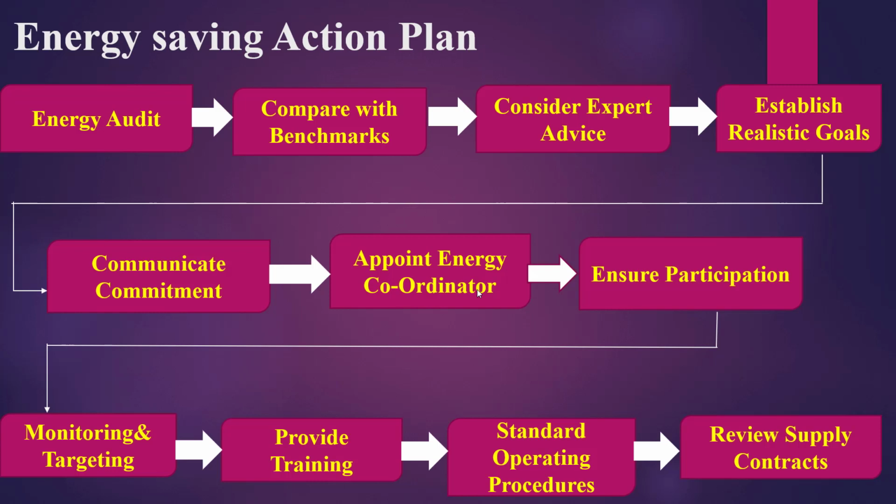Ideally, you will have installed a system of sub-meters serving different areas or departments of the hotel. Reading these sub-meters on a regular basis, daily or weekly, will help in diagnosing where and why any unexpected consumption occurs. It will also enable you to recharge energy costs both internally to cost centers within the hotel and to any independent operators who may be using the hotel premises, such as a shop or hair salon. This will place accountability for energy costs on those who are responsible for usage and will give them a financial incentive to ensure that energy is not wasted.